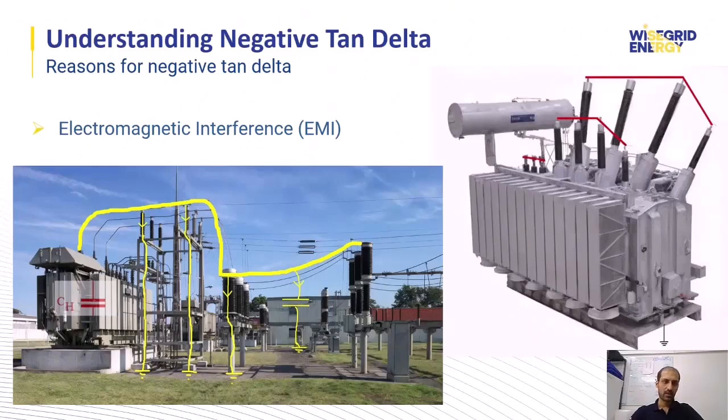And if we measure CH and CL, the tan delta and also capacitance of these equipment come into the measurement, and we are measuring all of the capacitances in parallel with CH and all of the losses.